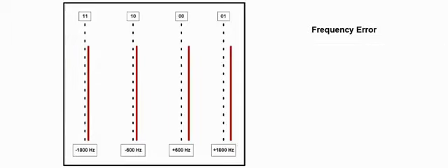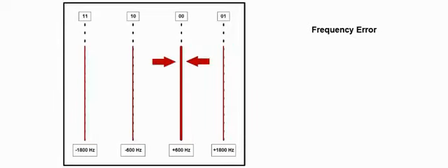In contrast, an analog frequency error meter would count the average frequency of the signal by counting the number of cycles in a given period. Say, for example, the signal contains a large number of zeros. The average deviation detected by an analog counter would include a large number of counts with a 600 Hz offset. This would skew the results with an erroneous reading. Thus, an analog offset meter cannot be used for this measurement.